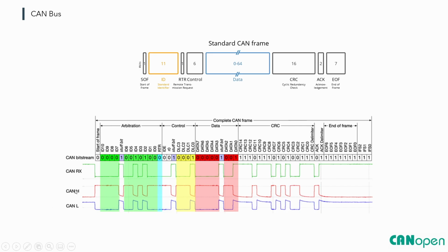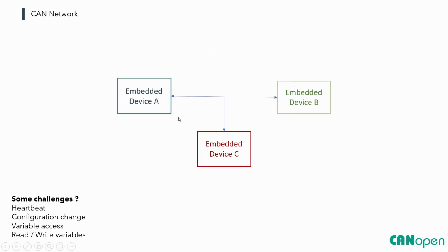On the other hand, let's talk about the reception mode as well. If the CAN physical layer receives a CAN H and CAN L signal, it translates those to a CAN RX signal, which, if you want to imagine it, can be like a simple UART reception. So the physical layer can transmit information and receive information for the CAN controller. All right, let's go to the next slide.